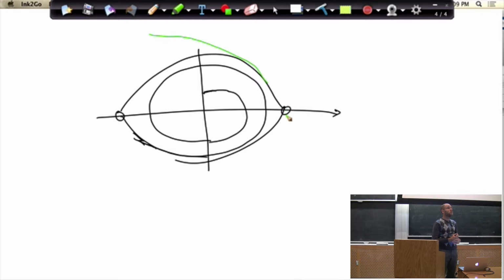Yeah, so our controller is only made to control the energy of the system, not its position. But the whole reason we selected this controller is because the entire homoclinic orbit has the same energy. So if the controller is good, you'll stay on the homoclinic orbit, but you have no guarantee as to where. So once you get near the fixed point, you need to switch to that linearized controller to stay there. Exactly right. So when you get here, if someone were to perturb me here, I will still stabilize the homoclinic orbit, but I'll go all the way around and then come back and visit again. But the second part is exactly right too. Once we get close, we already know controllers that'll work. So the idea would be to switch to the LQR controller when we get close enough.